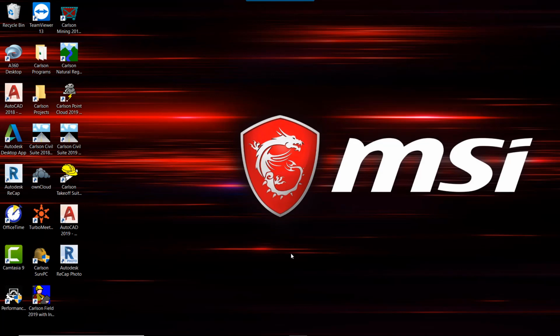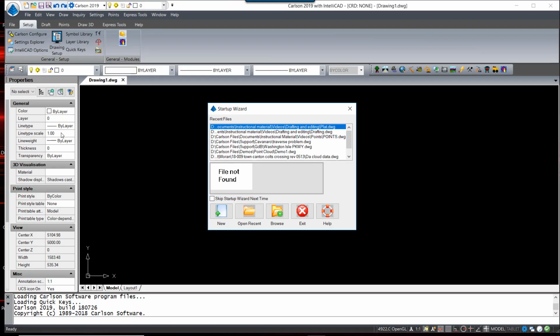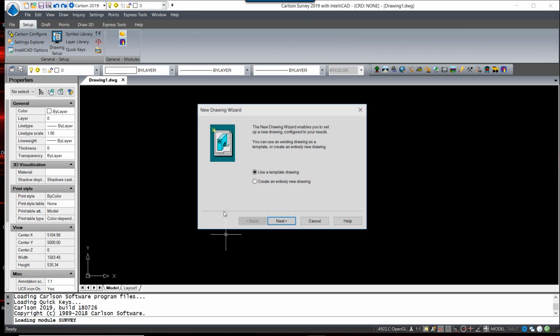In this video, I'm going to follow a step-by-step procedure to make a simple plat based upon field information. We'll start by launching Carlson through the icon on the desktop. At the Startup Wizard, I will hit New to create a new drawing.